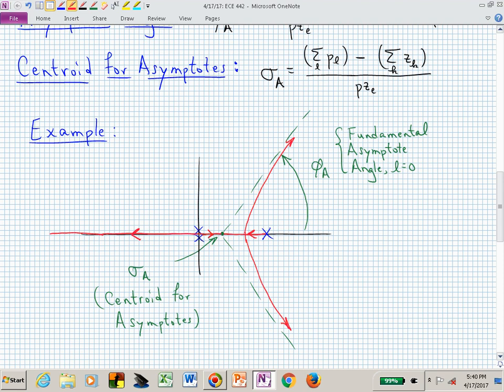Do those two poles still break away at the origin? So now the two poles at the origin, one is going right and one is going left, right at k equals 0. As we crank up the gain k a little bit beyond k equals 0, one goes right and one goes left. They stay on the real line. It's not curved or anything. There's nothing curved at the origin. They're staying on the real line. One goes right and one goes left. The only curvature happens after the break between the one at the origin and the one in the right half plane.